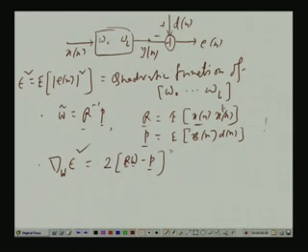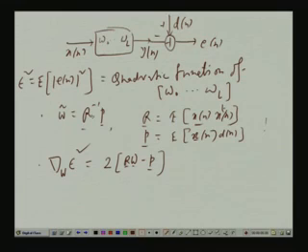Now, one thing is that you can find out the optimal filter directly by R inverse P, but suppose you do not have to follow this path. Suppose you do not know how to compute the inverse of a matrix. We can propose an alternative method, which is an iterative method, so that as the iteration progresses, finally, the filter weight W converges on what is called the optimal weight.